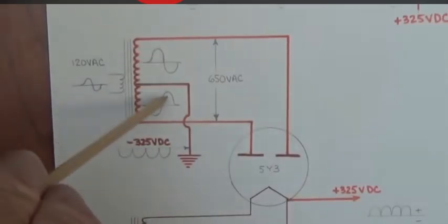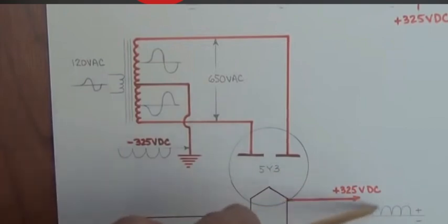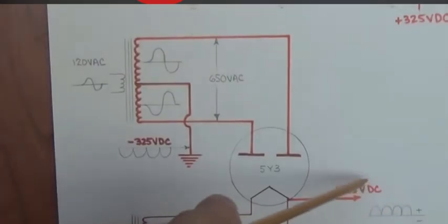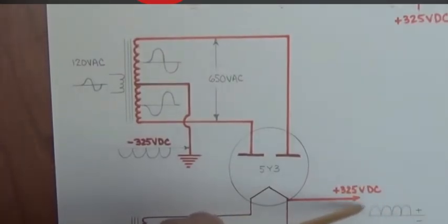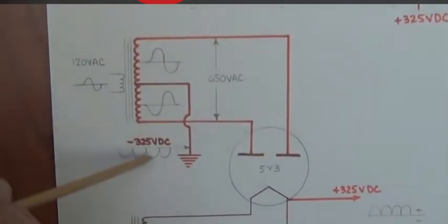Over here is the other output, and it is all of the tops. The tops of the curves are sent by these diodes out this wire, and we end up with this type of output. All the tops of the curves, it's all positive. Again, a lot of ripple, but we're going to take care of that. We're going to solve that with our filter capacitors and some other components in our amplifier. We will smooth these ripples out.